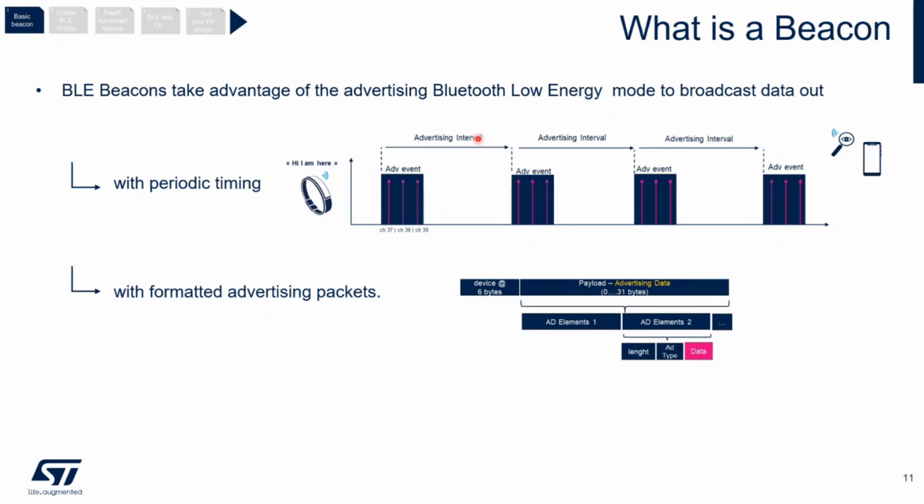By the way, we'll see this later on during the periodic advertising with response demo. So a beacon uses the concept of advertising interval to push data at some specific timing over the air, and the smartphone which is scanning, the client, is able to collect the data. And what are the data we have to push over the air? Here again, as we are talking about legacy advertising, the advertising data payload is up to 31 bytes.